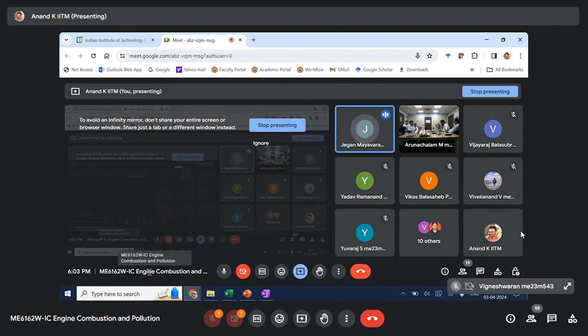The reason being, every control, that is fuel injection, exhaust valve actuation, cylinder lubrication, is dependent on the encoder signals. That is why we always have exact 0, and the error margin allowed is also 0.02 degrees, because if we go beyond that, we get an encoder failure alarm. So I just wanted to understand this difference in the reference TDC. Is this because it's a slow speed engine, or for any other reason? I just wanted to have your concurrence on this.